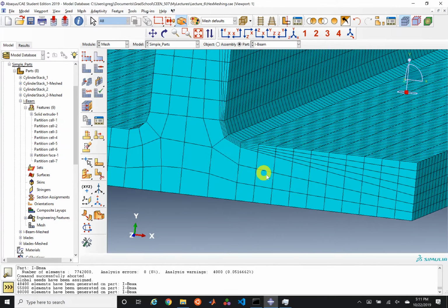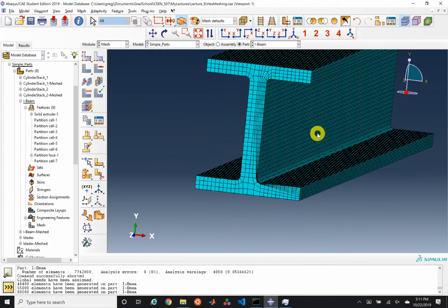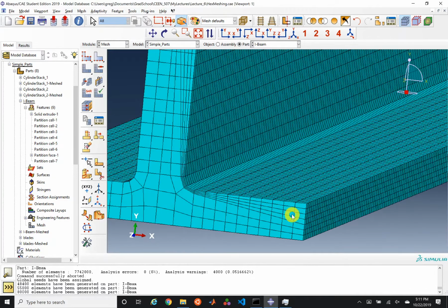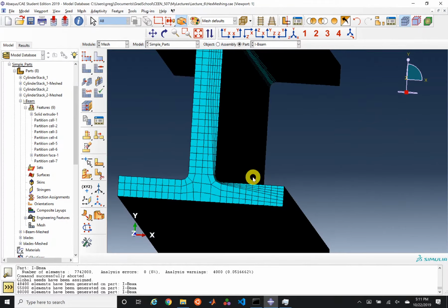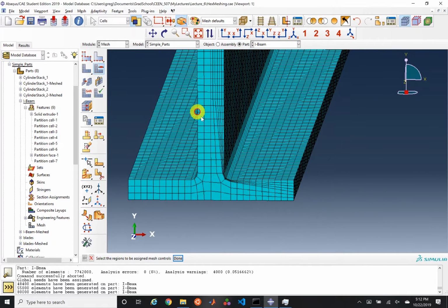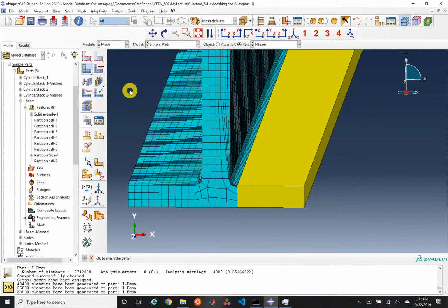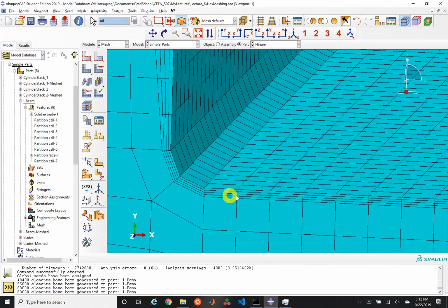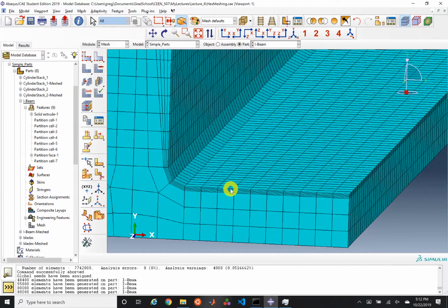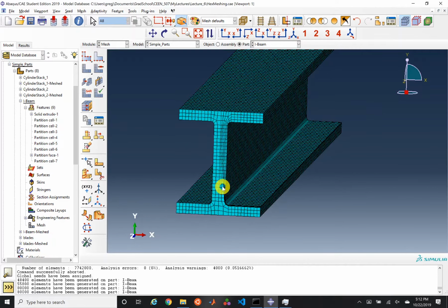If you didn't want those, obviously we could have partitioned this entire face the entire way along and put those elements through, because obviously some of these elements may not be of high mesh quality. But this is also where, if we remove this constraint of having to be structured on one of these sections, to say only being swept, it's now able to handle this idea of this coming through. So anyways, there are some various different things you can play around with constructing these meshes.